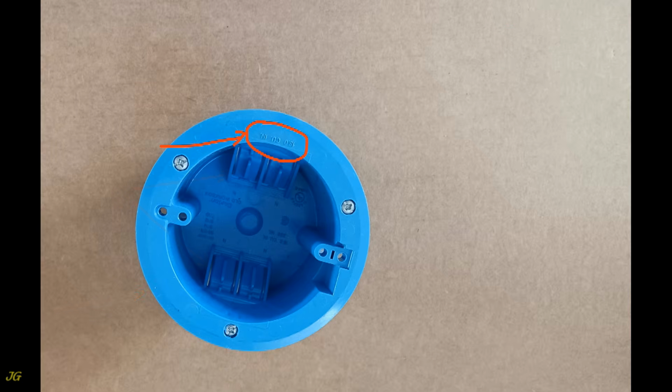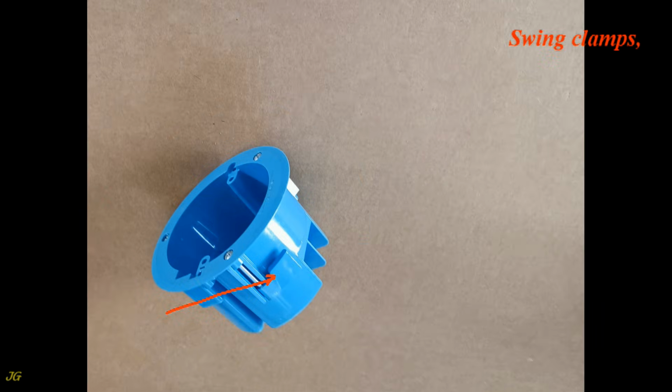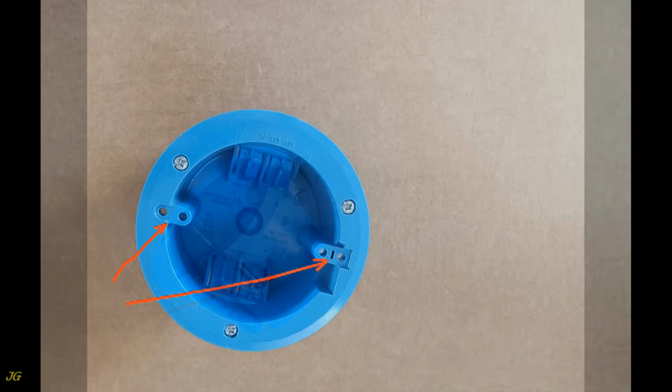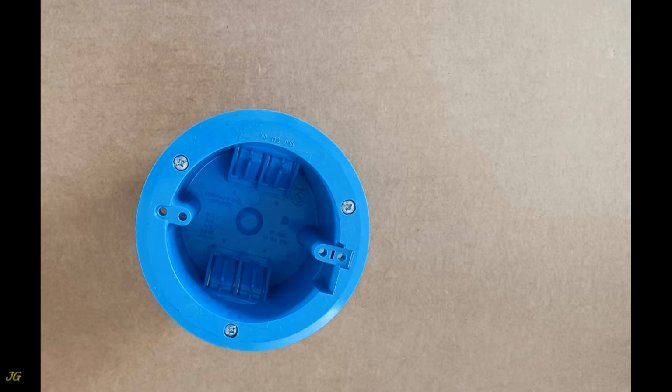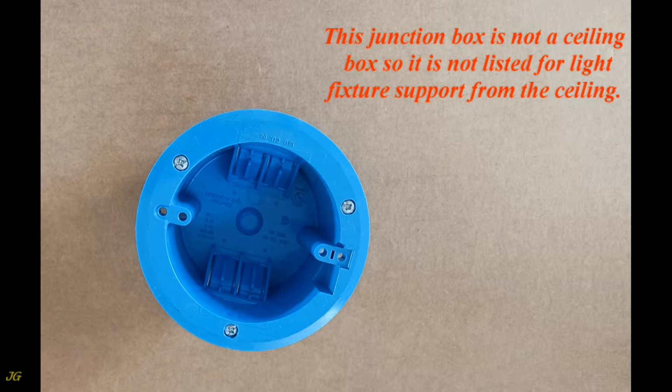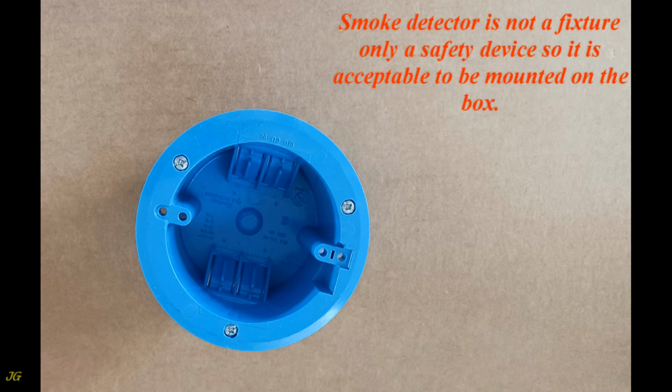Capacity of the box. Clamping windows. Swing clamps screws. Swing clamps. Holes for screws securing the light fixture or device. This junction box is not a ceiling box, so it is not listed for light fixture support from the ceiling. In the ceiling, this box can be mounted as a junction box or a support for smoke detectors. A smoke detector is not a fixture, only a safety device, so it is acceptable to mount it on the box.